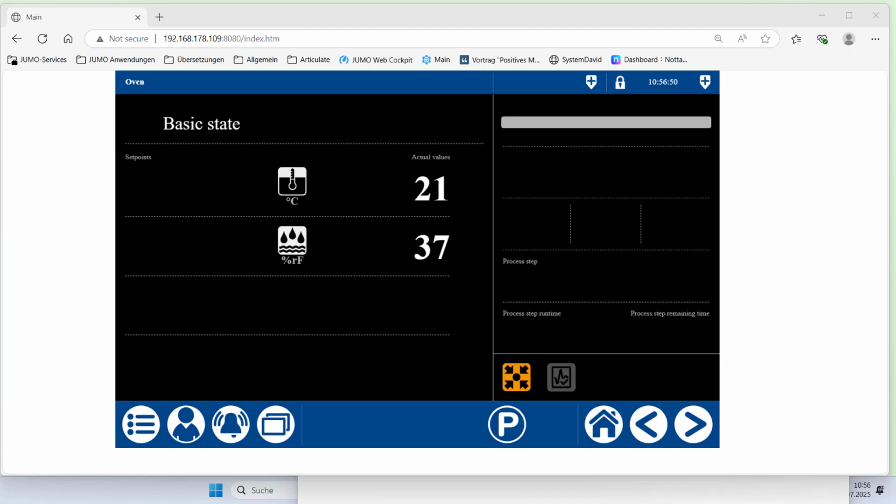You are now in the generator screen. You use the generator to specify set points as profiles and to control additional actuators during the profile sequence. Imagine that you are operating a chamber for treating samples. Sometimes you only need to specify a temperature profile, which is then regulated by a controller. However, you often also need to regulate to a defined humidity. At the moment, the chamber is not in operation and you can see the current temperature and humidity in the chamber here.